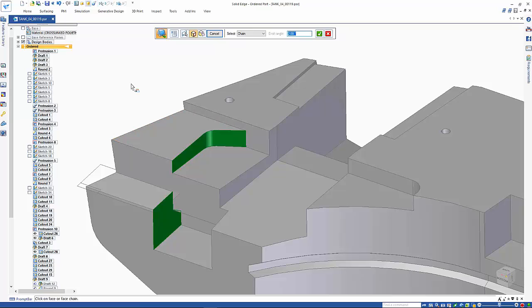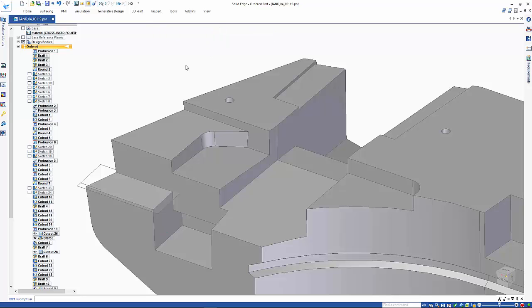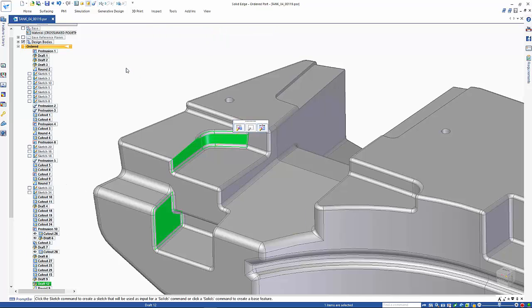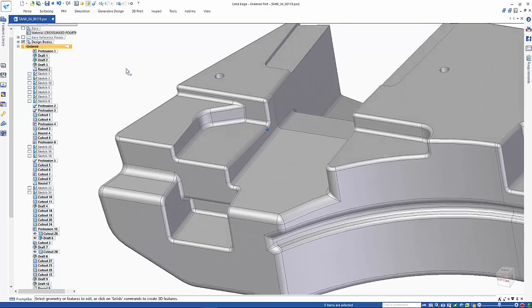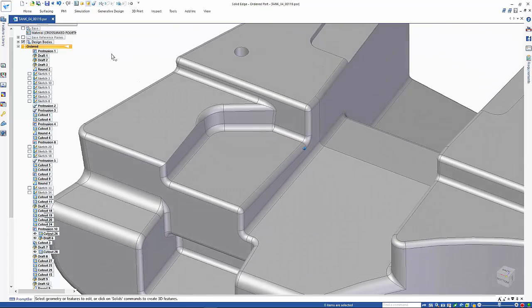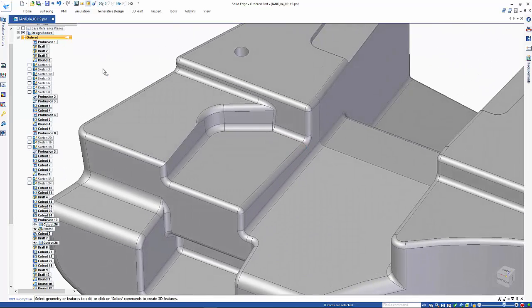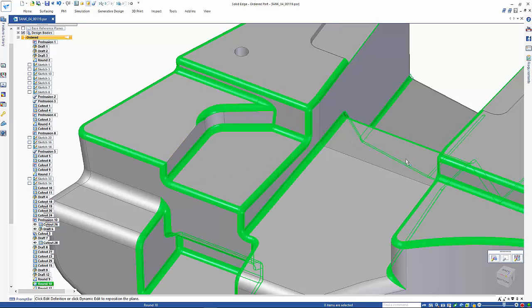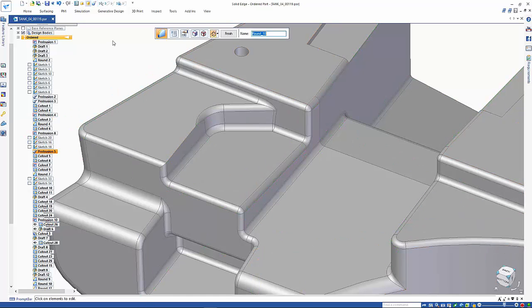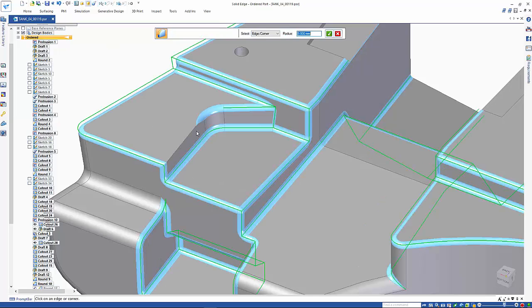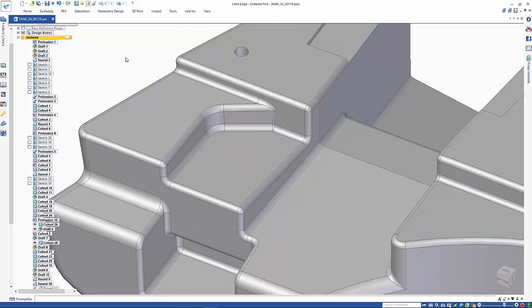Imagine if we had not made this final check and just assumed the faces were aligned. What would it have cost our company to repair the tooling when it was discovered that the tank didn't fit? Note that adding this draft has impacted the rounds. Did we make the changes to the rounds? No, but in history-based modeling, as one feature is based on another, one change can in fact turn into multiple changes. This again requires us to modify existing geometry to add these rounds back to the edges of the cutout.